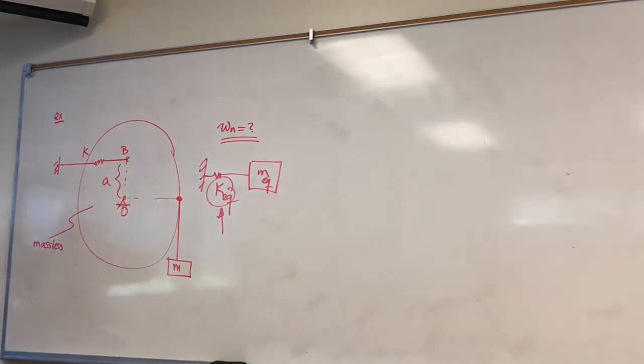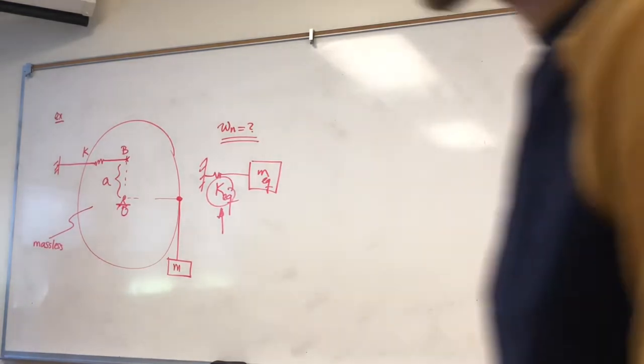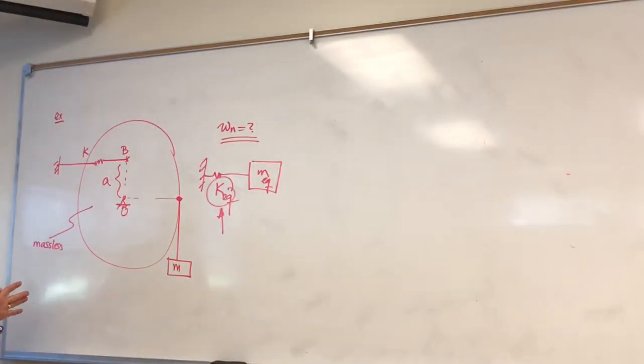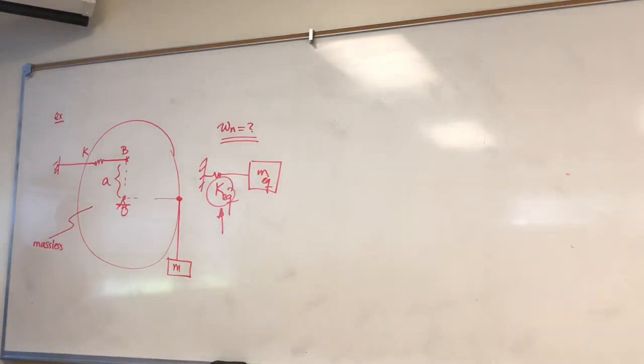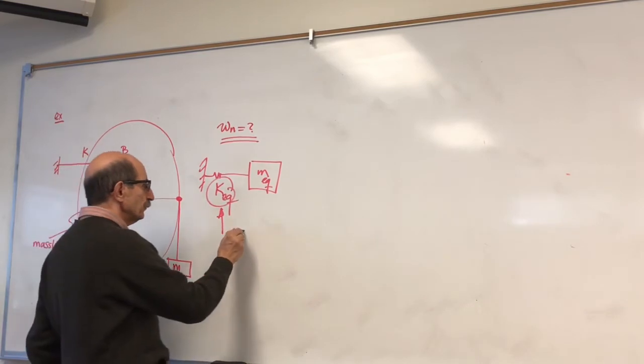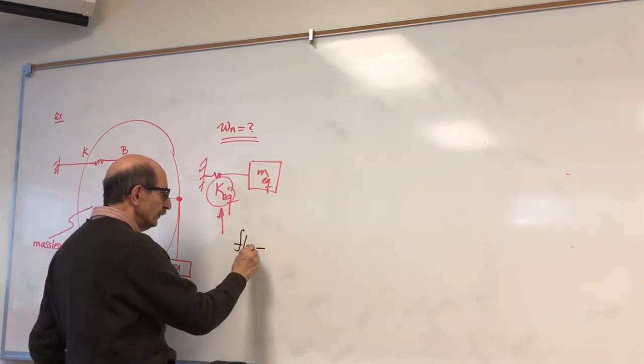Well, thinking about all the concepts: series, I don't have two springs here that are in series or in parallel, so forget about that. Superposition, useless. The only thing that really helps me is going back to the basic concept of stiffness. But even that, stiffness is the force that causes a unit displacement. That doesn't do me any good. However, I remember the concept of flexibility, which is the inverse of the stiffness.